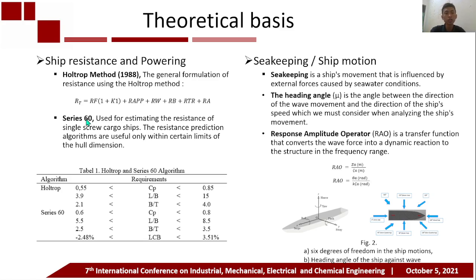The other method is the SER16 resistance method. It is used for estimating the resistance of single screw cargo ships. Table 1 shows the Holtrop and SER16 algorithms. There are several requirements for a ship to be analyzed with this method.